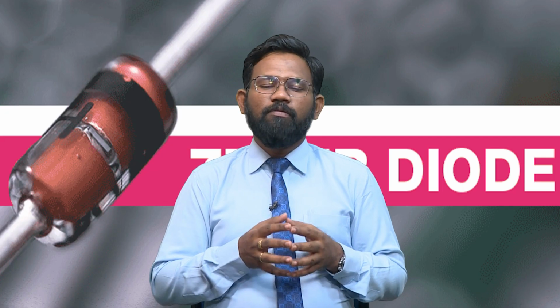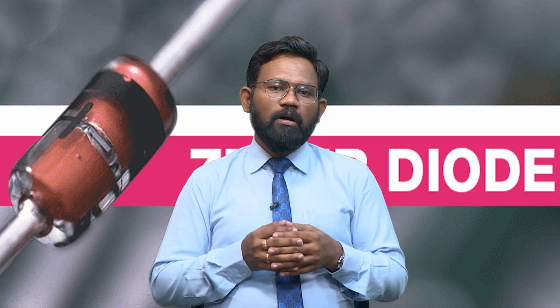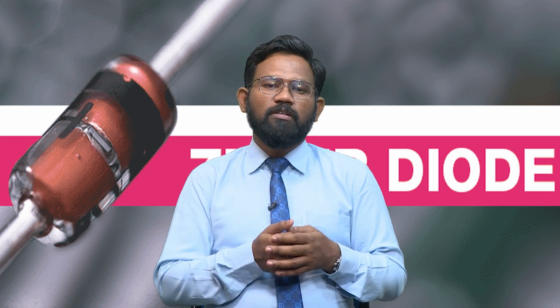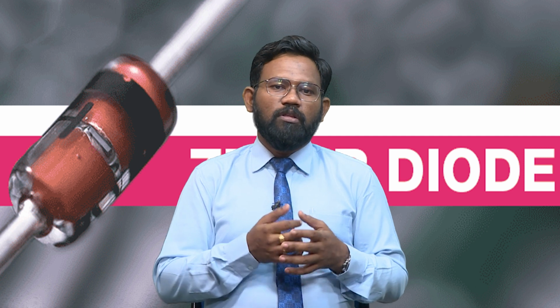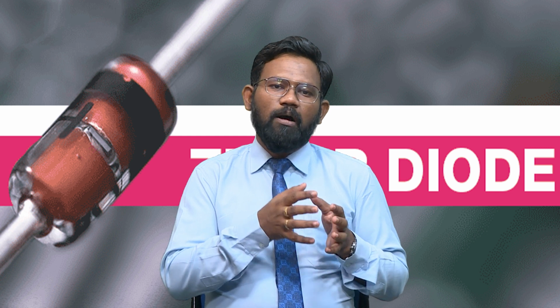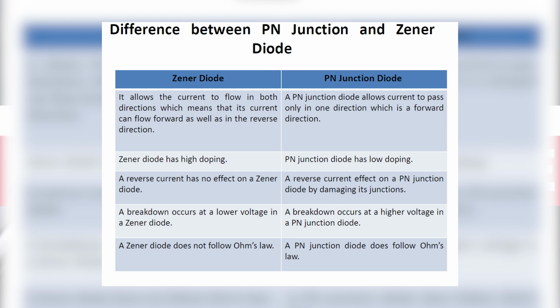As we have seen in the VI characteristics of the Zener diode as well as the p-n junction diode, the breakdown occurs at a very high voltage in the negative direction in a normal p-n junction diode, whereas the breakdown occurs in a Zener diode before the avalanche breakdown of a normal diode. So in this way, less voltage is required to be applied in the reverse direction for a Zener diode. A Zener diode does not follow Ohm's law. This is a very important point here. A Zener diode does not follow Ohm's law, whereas a p-n junction diode follows Ohm's law.